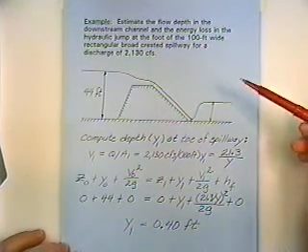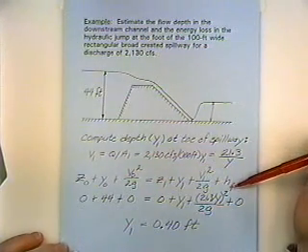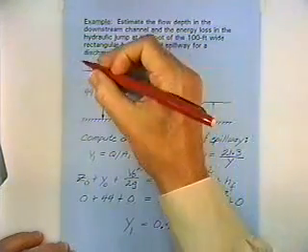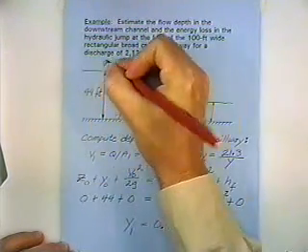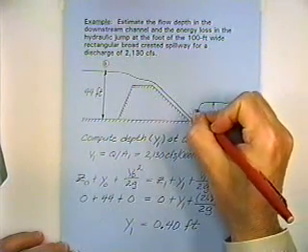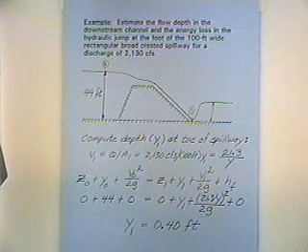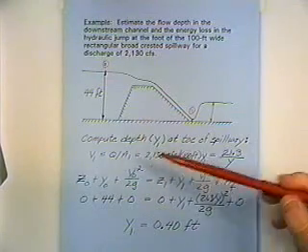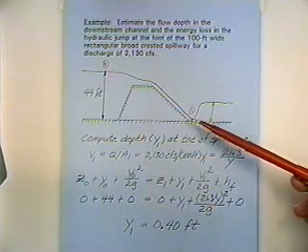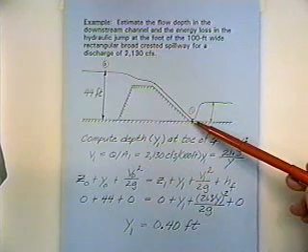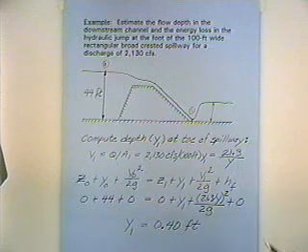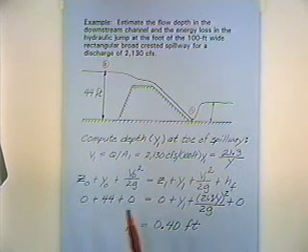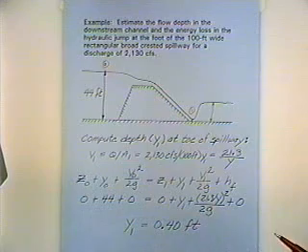So we're plugging into the energy equation between two points. Pick a point there. I called it point 0, and picked a point here and called that point 1, and apply the energy equation between those two points. Velocity is discharge divided by the area. If we take the discharge there and divide it by the area there, we're going to have the velocity. So I've got an expression for the velocity.